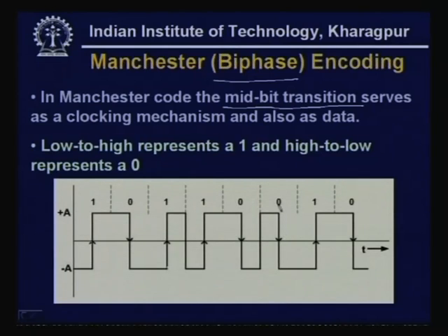However, when you have alternating zeros and ones, then as you can see the number of transitions is 1 per bit. However, you have got enough transitions. This is Manchester encoding, where the signal levels are represented by the transitions. Essentially it is going from high to low or low to high in the middle bit position.